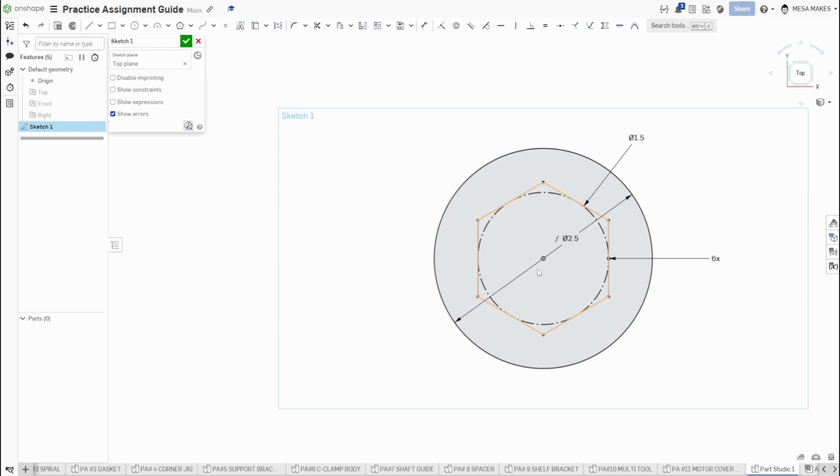I'm going to draw, and I know on my drawing I have construction lines, and I'm going to draw one right now just to show you how you could do this and not do dimensions by using what's already existing. So I'm going to draw a line, and that line needs to be 2.25 because that's how far away the center of my circles are. And both of my circles are going to be concentric. So I can press C, shut off my construction with Q.